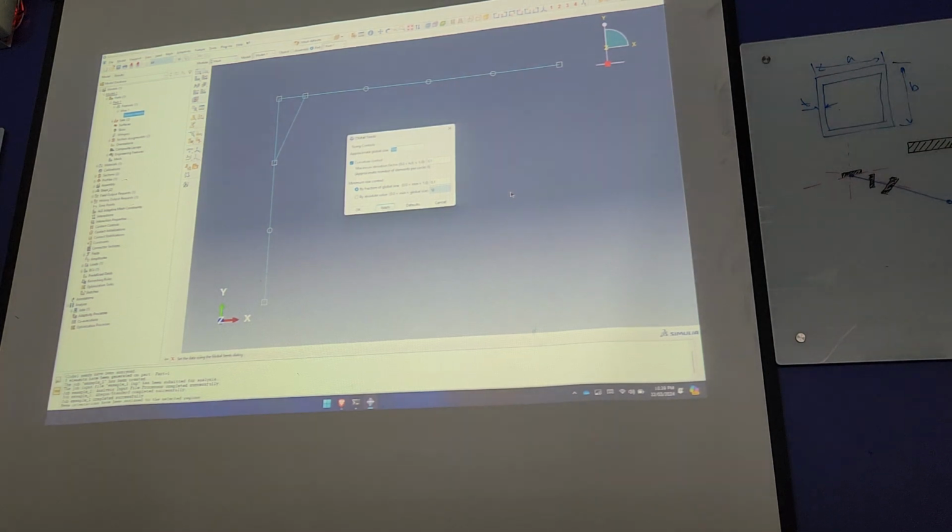You can't have more than one, because if you had another node there, you'll have a problem, because once you put a load, that node will just pivot. It will be hinged. Basically, this is hinged. That bit there is hinged. That's basically what happens at every node. There, there, there. So you can't have a node in the middle for truss.